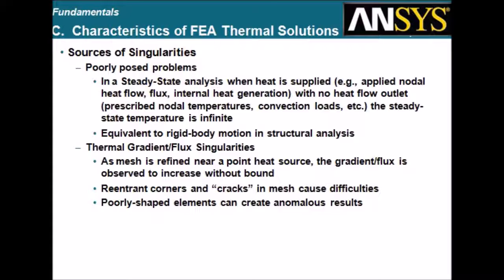Thermal gradient/flux singularities. As mesh is refined near a point heat source, the gradient/flux is observed to increase without bound. Reentrant corners and cracks in mesh cause difficulties. Poorly shaped elements can create anomalous results.